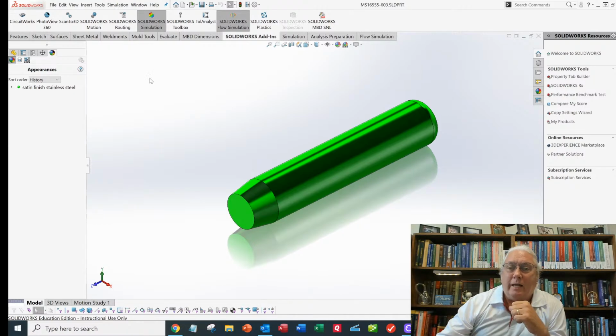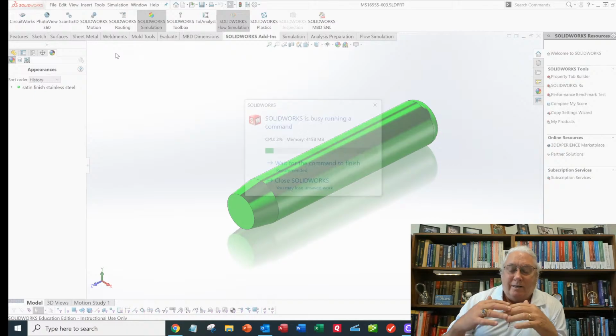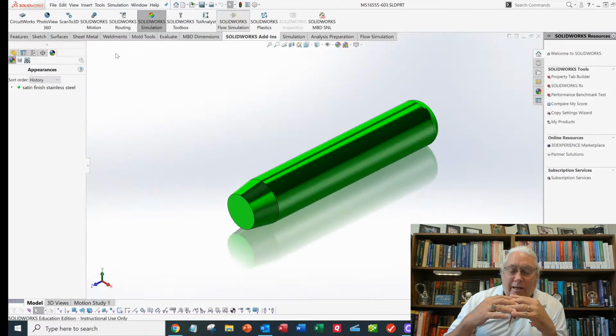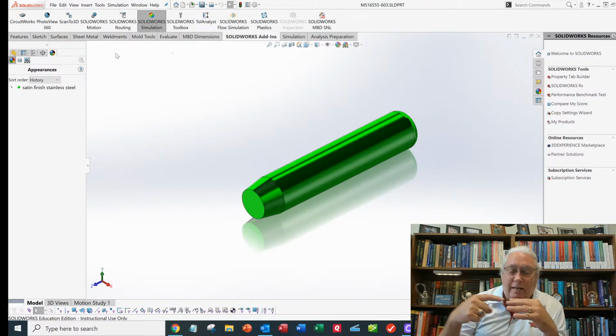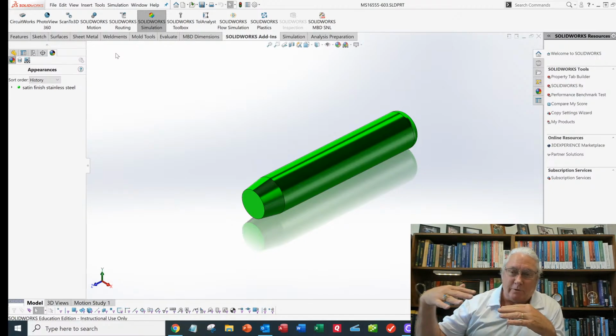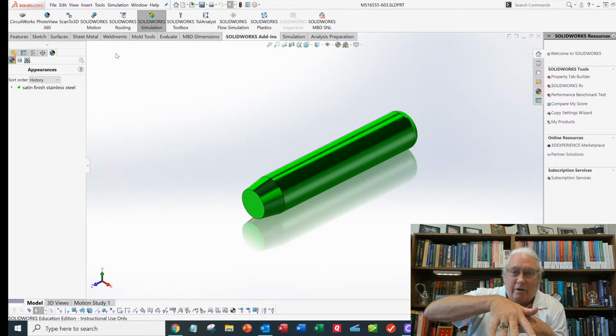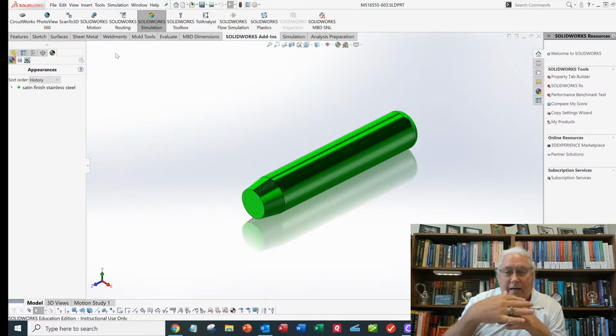And composite, as you know, is definitely anisotropic. It has different material properties in different directions. What this module allows you to do is define those material properties, not only in X, Y and Z, but also align or define them for different layers of composite material. So if you've got a fiberglass weave that you're making an epoxy composite out of, you might run your glass fibers in the 0 degree direction, then lay up the next layer at 90 degrees, then the next at 45, and another at minus 45, and do those alternating layer stack-ups.